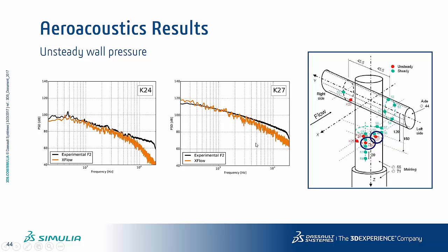And I think it's important to mention that most of the codes, and especially the Navier-Stokes codes, can have a very quick cutoff frequency when the mesh is not fine enough, when you start being too diffusive, and you don't capture the high frequencies necessarily very well. So in that case, a lot of codes had a big cutoff frequency very early, too early. You can probably compare with the reference I left previously, but XFlow results were among the best we could see during this workshop, showing that Lattice-Boltzmann is a very good match for this kind of problem.